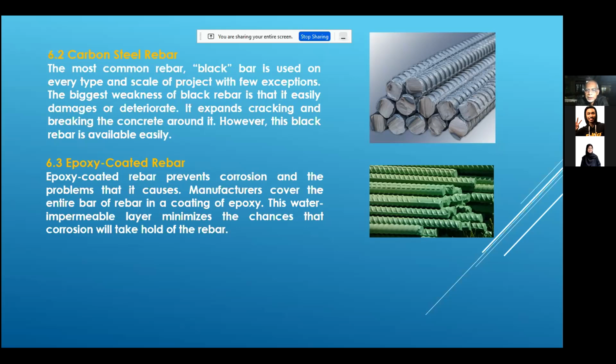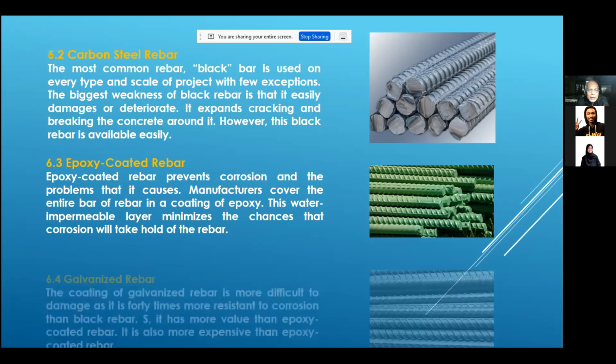So they create some holes along the rebar, and then it is subject to rust. I mean, the so-called epoxy coating is not that functional, so a lot of damage is done during handling. So they are not so much encouraged to do this, right? Unless you want to use stainless steel. I'll show you stainless steel afterward.